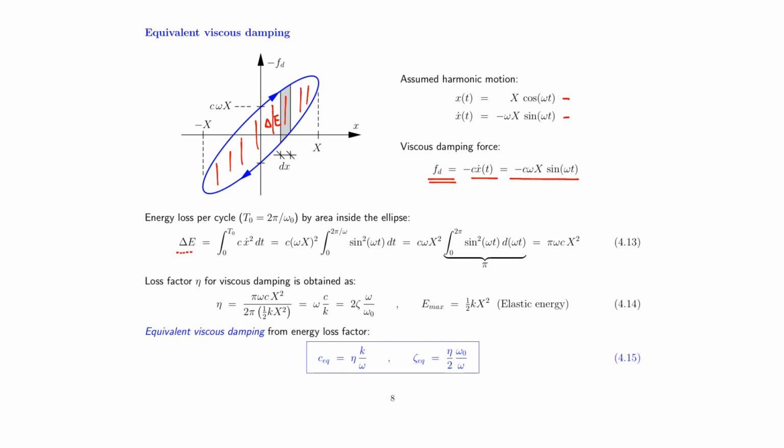So we defined the loss of energy as an integral over a period, velocity times Fd integrated over time. We did the transformation into a contour integral simply to identify that the dissipated energy is equal to the area inside the curve. Sometimes it's quite easy to estimate the area inside a hysteresis loop. In other cases like this, where we have a nice mathematical formula for our damping force, it's easier to evaluate the dissipated energy directly by mathematics and solving the integral.